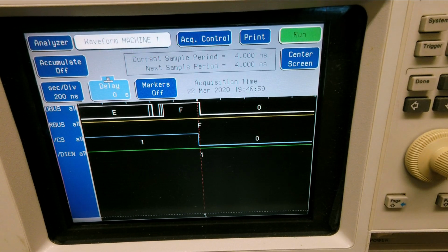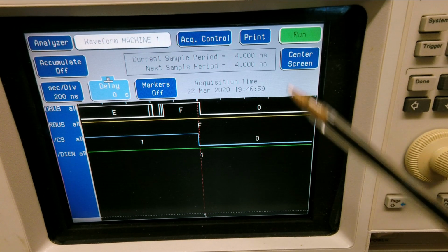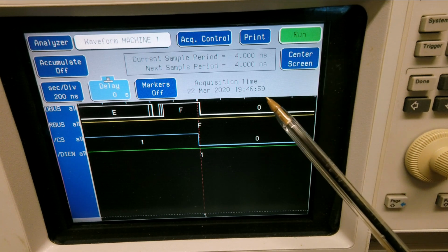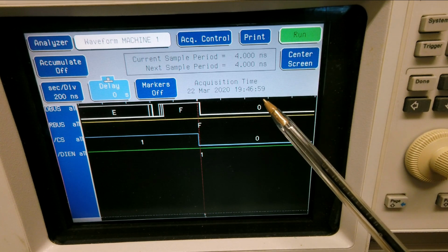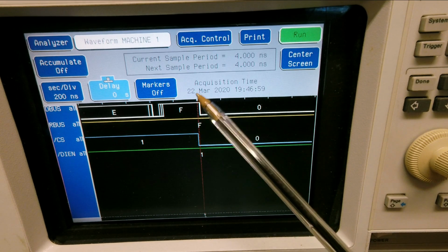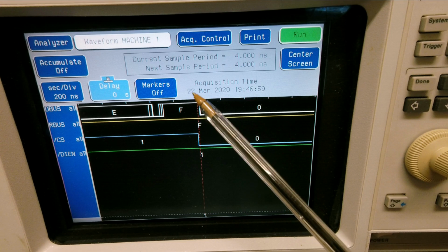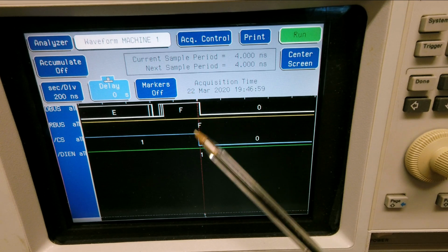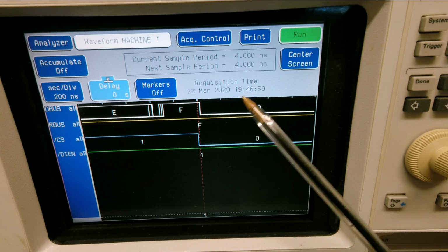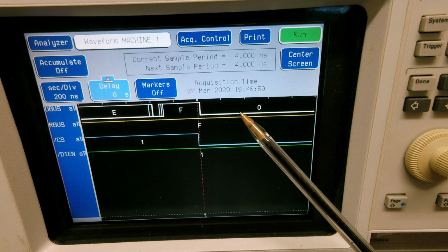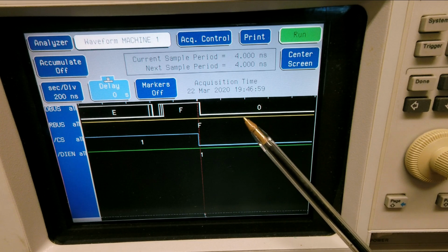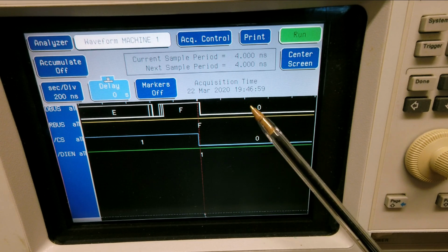Right, okay, so you can see immediately we've got a problem, because the data bus is inverted, so this should be an F. You can see the chip select going low there. It was briefly an F before the chip select went down. We are getting the inversion, or whether that's actually true or not, I don't know, because it's inverting the 0 to an F. Let's try another number. I'll try putting 5 in there.